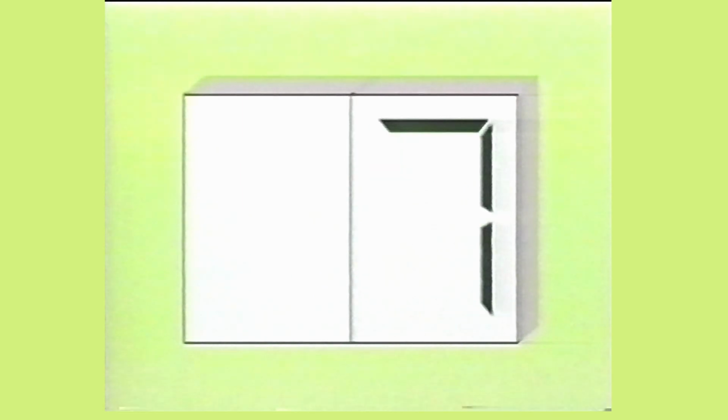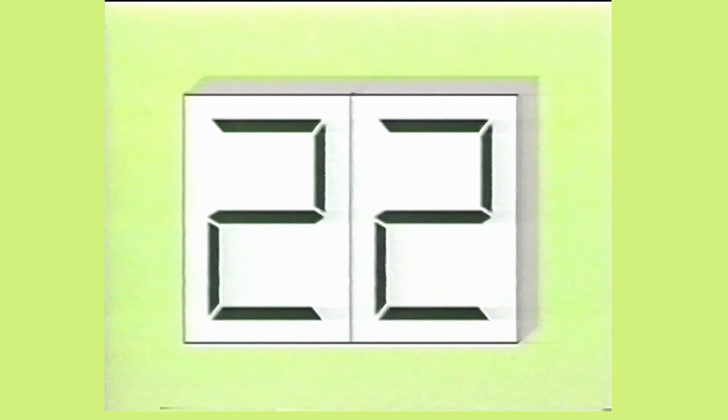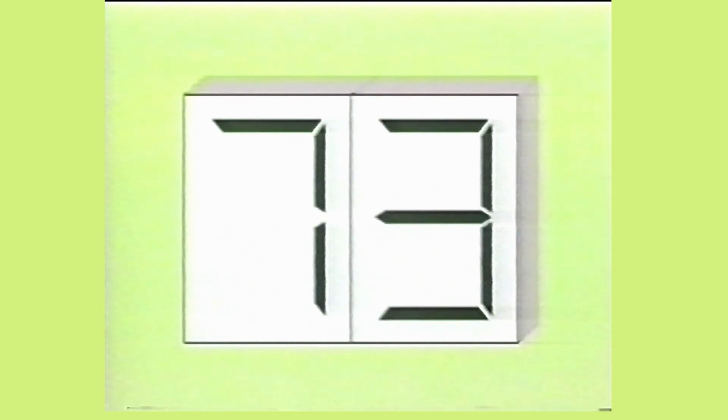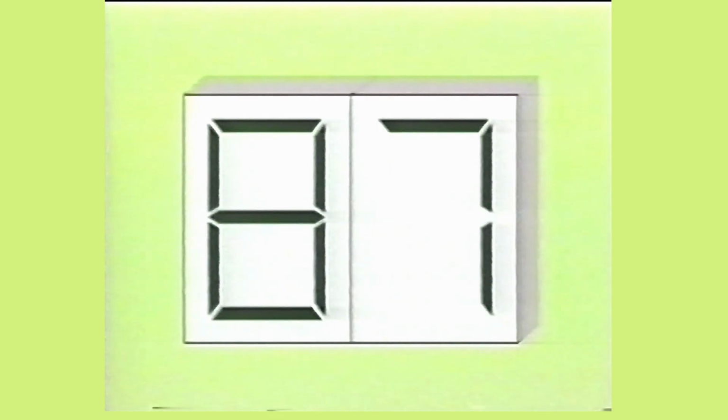The operation of the liquid crystal display is almost identical to that of the 7-segment LED display. By controlling the separate segments of the LCD device, it can be made to display decimal numbers 0 through 9. The recommended supply voltage for the LCD device is a 30-volt peak-to-peak 60 Hz square wave. The operating current is typically 125 microamps. The major advantage of the liquid crystal display is its obviously very low energy requirement.